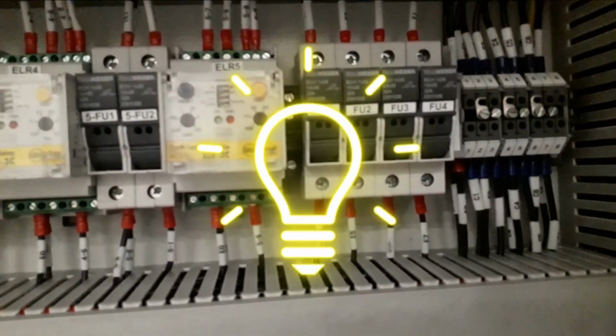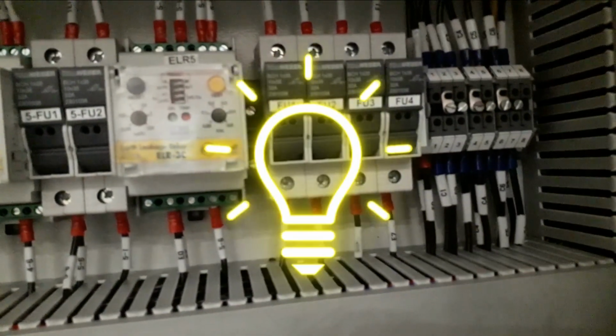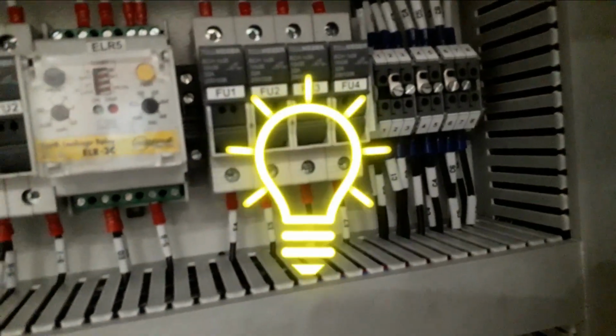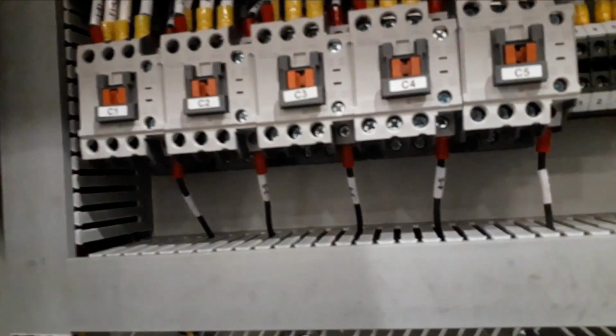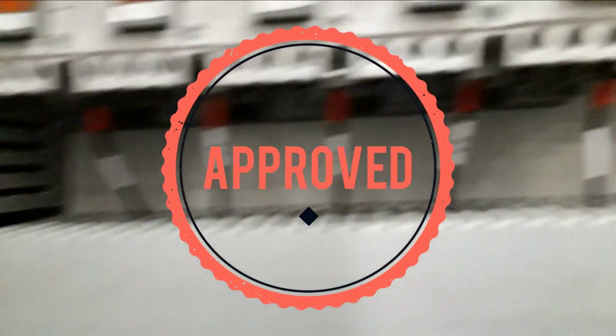Okay, so that is related to the indication lamp RYB, to identify the incoming supply if available or not. Okay, and then we also have the terminal block. It is related to CT. That's what you see here, X1, right? So that is the terminal block through CT. And then we also have the neutral terminal. Okay, and this will be the outgoing point for our customer cable, incoming cable. It will be from here to here.